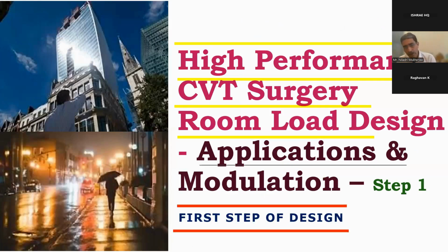So what I was telling earlier is that in these types of surgery rooms, the building load modulation is very, very important. If we go with some hypothesis or some thumb rule, it will really be a problem. You see the critical area which I mentioned, that is TRR, temperature recovery rate.